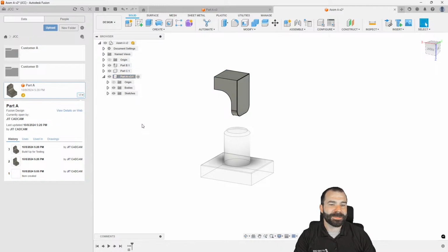If I activate this part, I'm no longer doing edit in place. I can even expand out the history of that part to manipulate this in real time, never actually pushing something back to the original file. Again, this could be a dumb solid. It could be a placeholder. You know, maybe the bolt is too long and we're going to machine it down. Well, I could bring it in and then we could change the specs of that bolt, right?